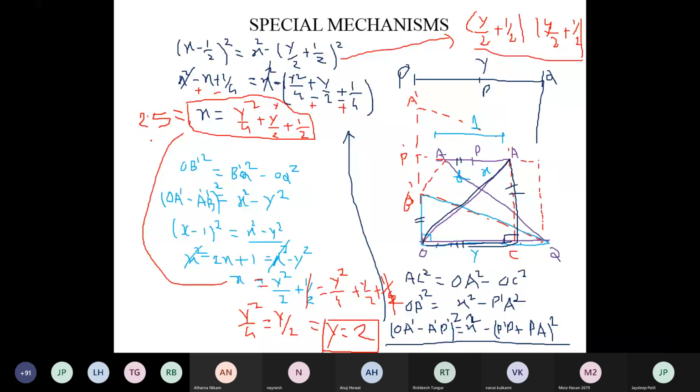Understand? Okay, hence we prove that the length of the links are in the ratio 1:2:2.5। Means यहाँ पे suppose AB 1 है तो x कितना आना चाहिए आपका? 2.5। This length is your 2.5 and y is equal to 2। When you take a proportionate, x का वैल्यू कितना होना चाहिए? 2.5 times of AB and y is equal to 2 times of AB। Got it? यस सर। Yes, sir.